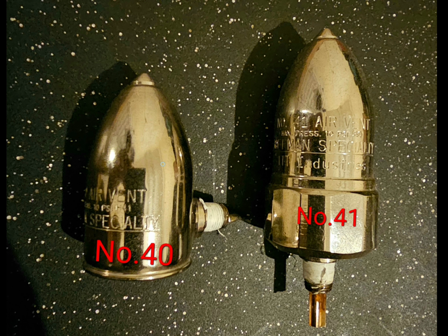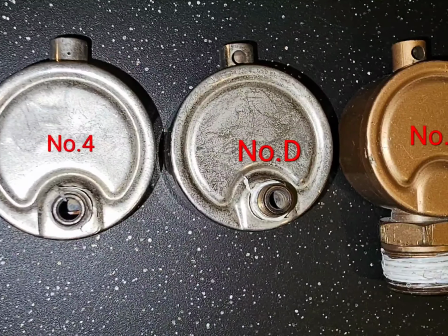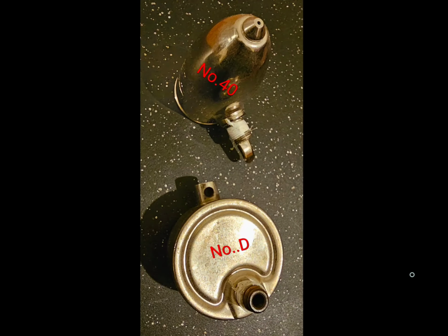Now, as far as cast iron radiators, the best vents that I've seen thus far are the Hoffman. Or you can stick with the Gordon number 4, or they have another size that's a little bit larger than this. I got one somewhere. I just don't know where it's at, and I don't know the number off the top of my head. But these will vent your radiator pretty well, and you won't have the problem of worrying about the float locking out or the thermostatic element locking out because of pressure. And I think I can get back into his video, and then I'll close this video out.